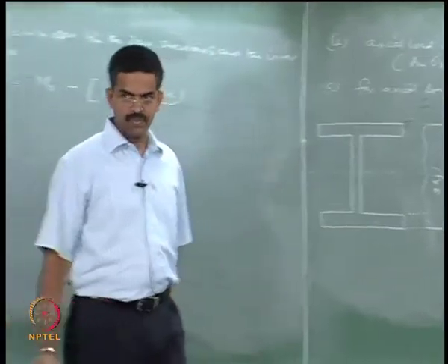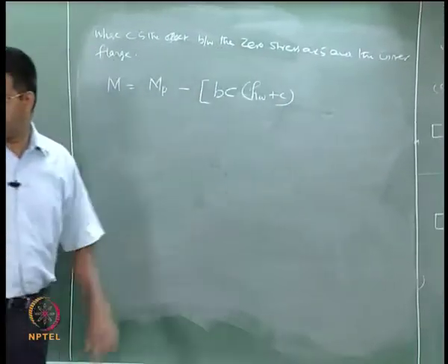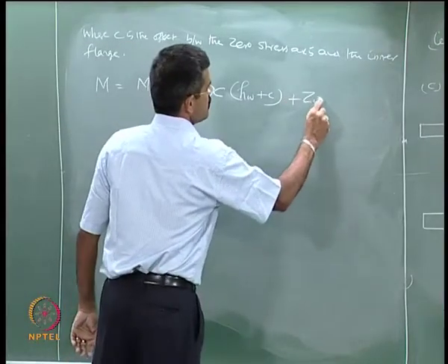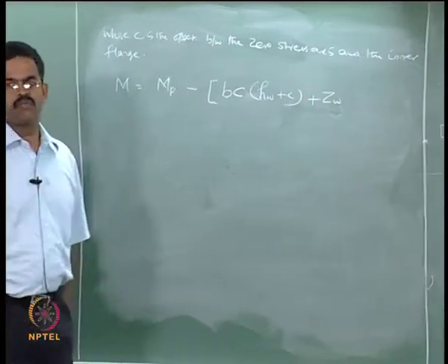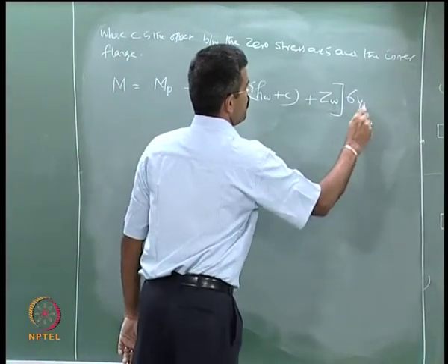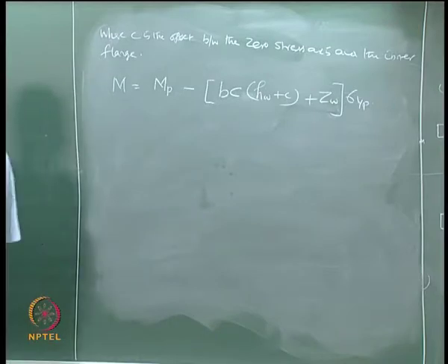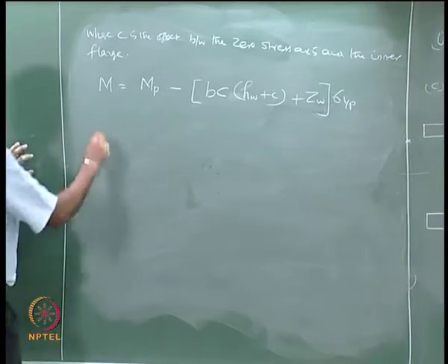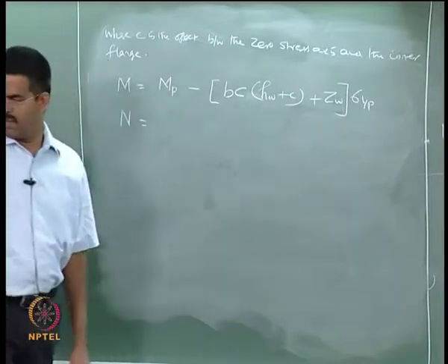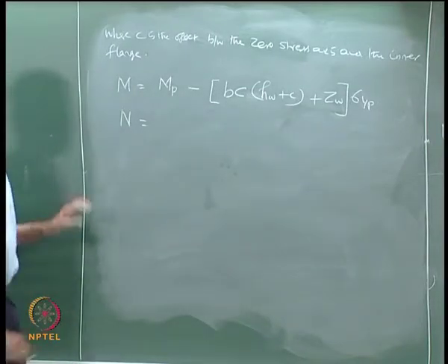Of course, plus the section modulus of the web alone, into sigma yp, and the axial force N, which is taken from the figure, is nothing but the area of the web.